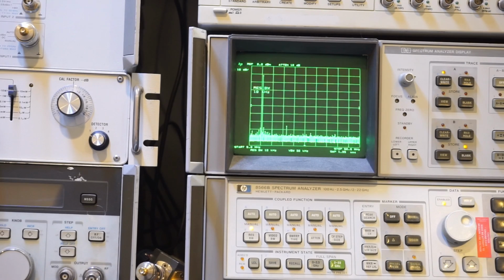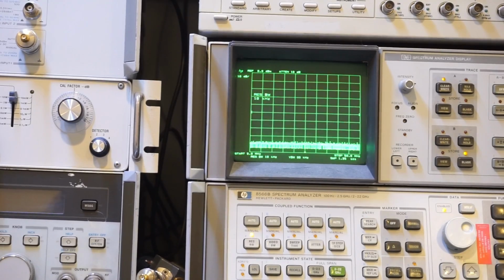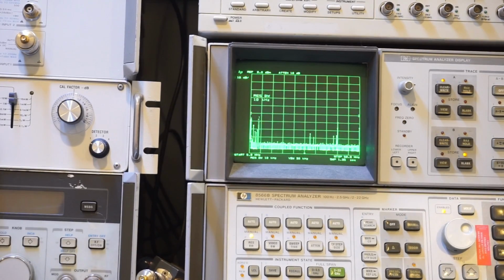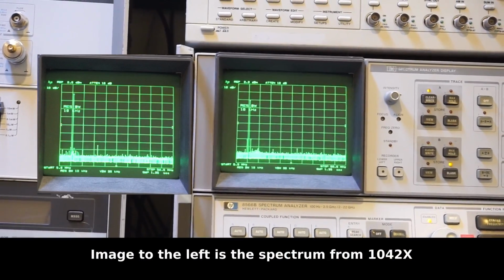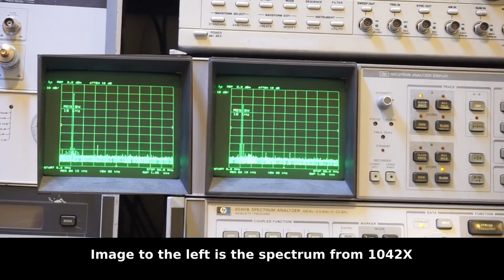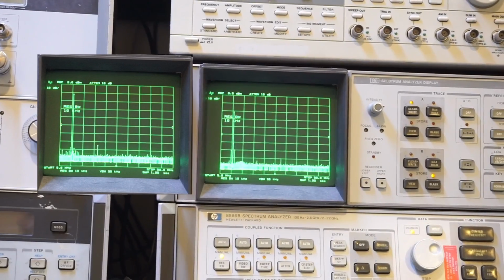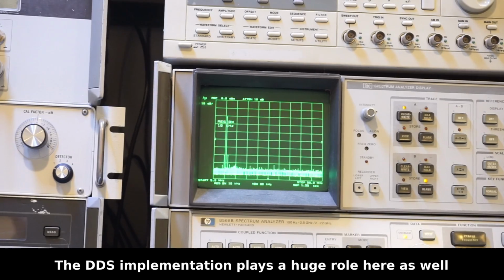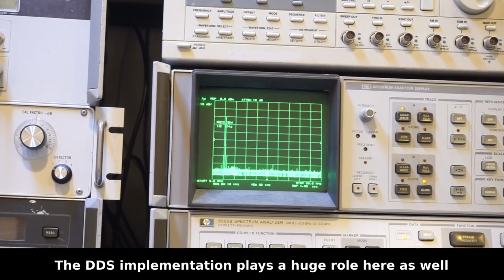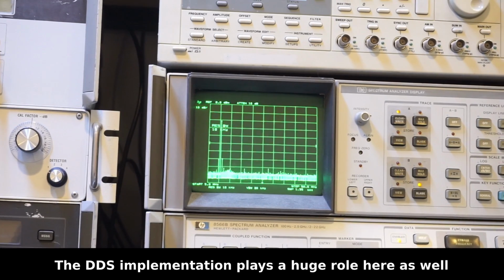Now let me swap out the output from the 1042X to the 962E. You can see that the signal is fairly comparable, but we did see a little bit more harmonics next to the 10 MHz signal, which is our main tone output. Potentially that was the difference between a 14-bit DAC and a 16-bit DAC. Now, of course, there are a lot of implementation details that could contribute to the differences that you see.